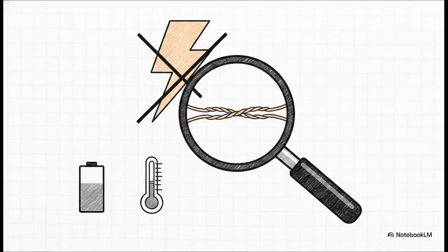But what if you want to use a basic component, like a simple thermocouple or a switch? Well, you use the simple apparatus thresholds. If the device generates or stores less than 1.5 volts, 100 milliamps, and 25 milliwatts, it doesn't even need formal Ex certification to be used in an IS loop. You just calculate its maximum surface temperature using this straightforward formula. Ta equals the barrier's max power output, Po, times the thermal resistance of the device, Rth, plus the ambient temperature, Tamb.